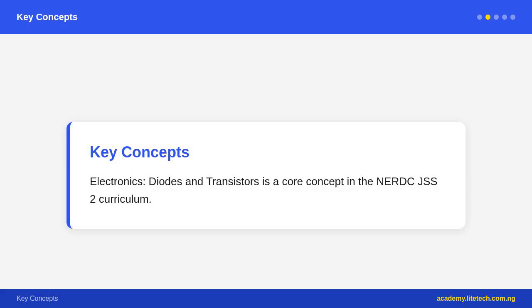A diode is a component made by joining an N-type semiconductor to a P-type semiconductor. This junction is called a p-n junction. The diode has two terminals, the anode, which connects to the P-type side, and the cathode, which connects to the N-type side. On circuit diagrams, the diode is represented by an arrow symbol pointing from the anode to the cathode, with a bar at the cathode end.